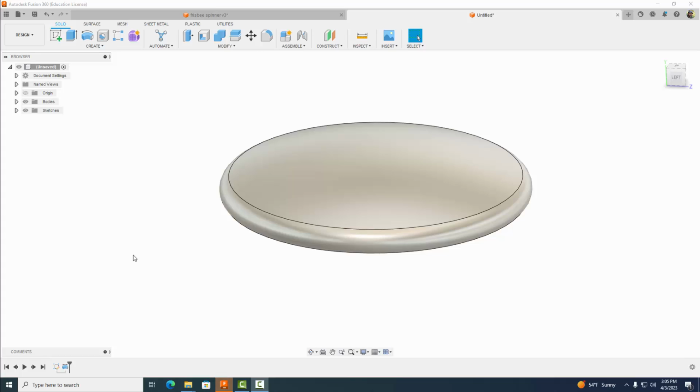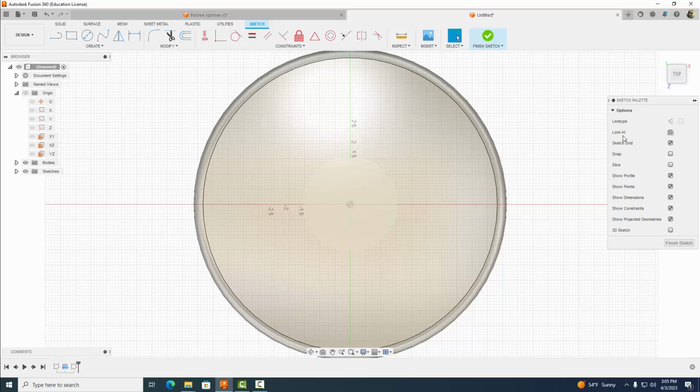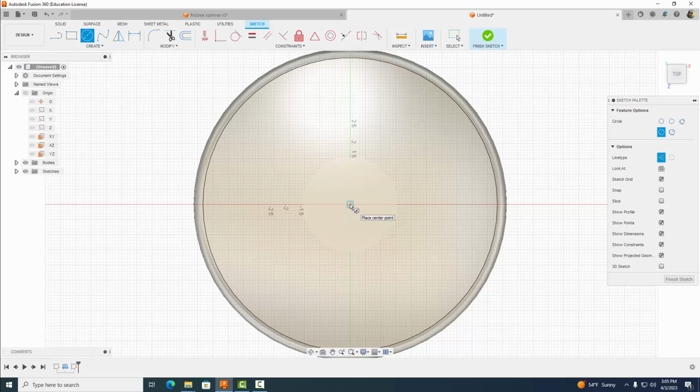All right, so now let's go ahead and add some custom text. So I'm going to come over here to origin, and not that one, but that one, that face right there. I'm going to start a sketch on that guy. Okay, and I'm going to create line type here of construction again, and I'm going to come over here to my circle tool, and I'm just going to drag out a circle with a distance of about 7.3 inches there and hit enter.